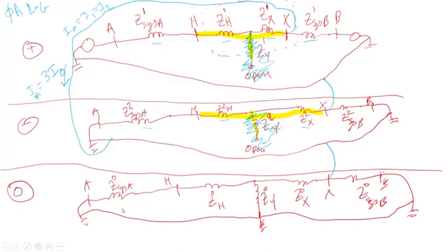So for the zero sequence, it's a little bit different because you have this impedance here in parallel with this impedance. Then whatever that equivalent impedance is, it is in series with this impedance here. So you would do the sum. Then that equivalent impedance is in parallel with the system B impedance.